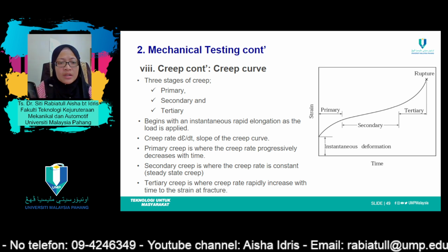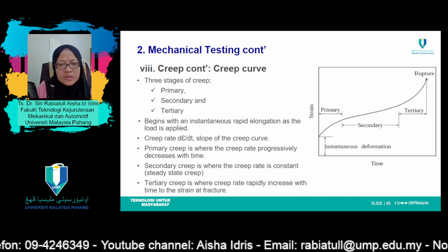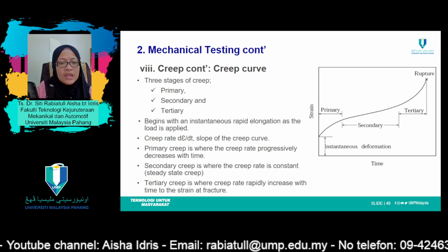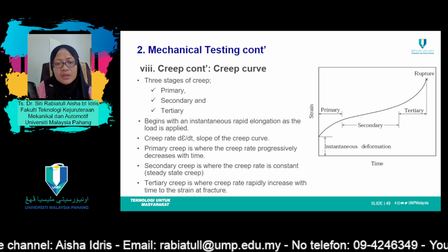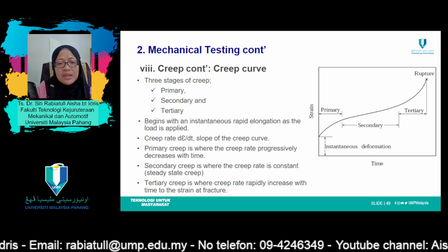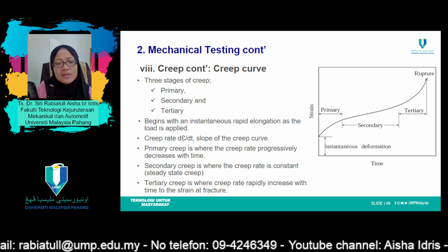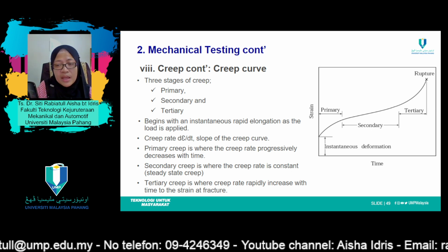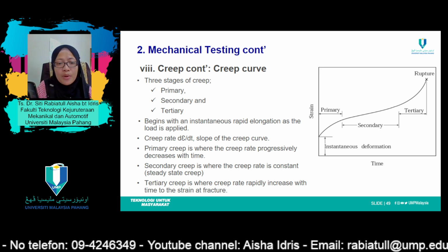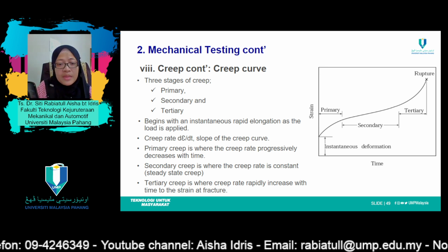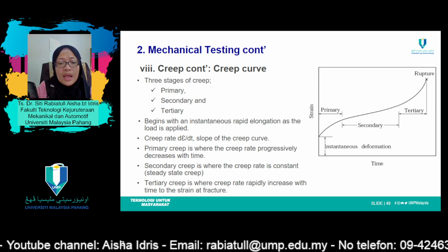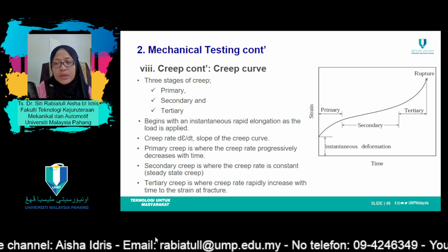Finally, for tertiary creep, there is an acceleration of the rate and ultimate failure. This failure is frequently termed rupture and results from microstructural or metallurgical changes, for example, grain boundary separations and the formation of internal cracks, cavities, and voids. Also, for tensile loads, a neck may form at some point within the deformation region. These all lead to a decrease in the effective cross-sectional area and an increase in strain rate.